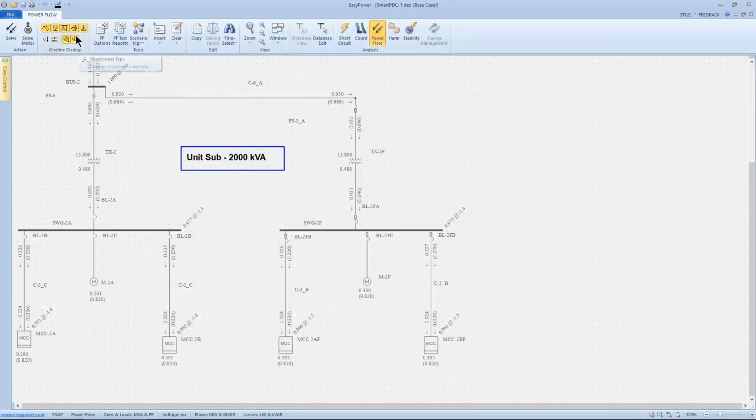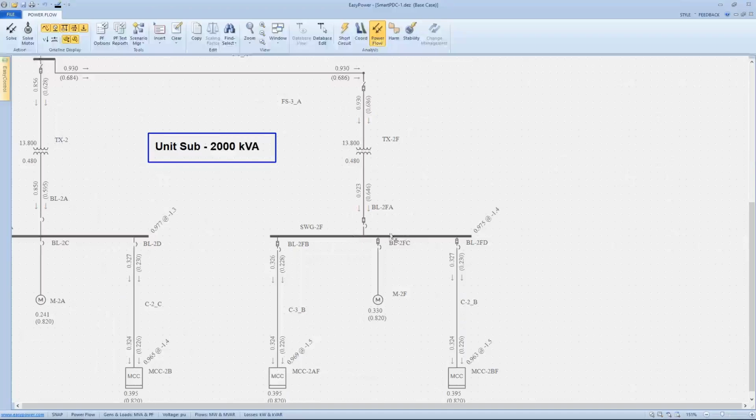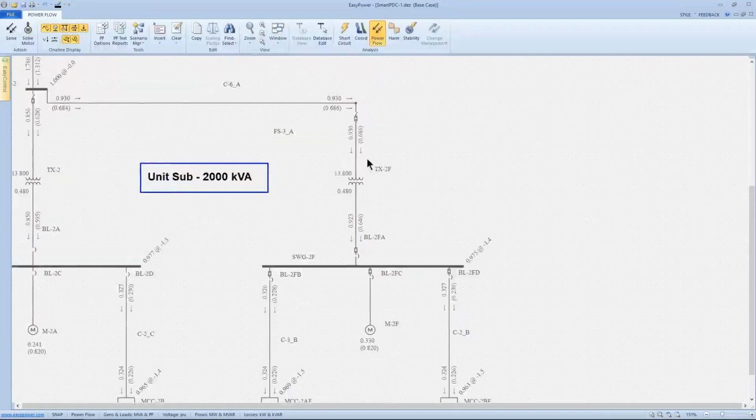The part I want to look at is voltage violations. If we have something that's dropping beyond a certain threshold, the tool can flag us on that. What I want to deal with is this initial drop, albeit not that great, but because it's something that's affected by the tap settings on the transformer, what is the correct way to deal with this?